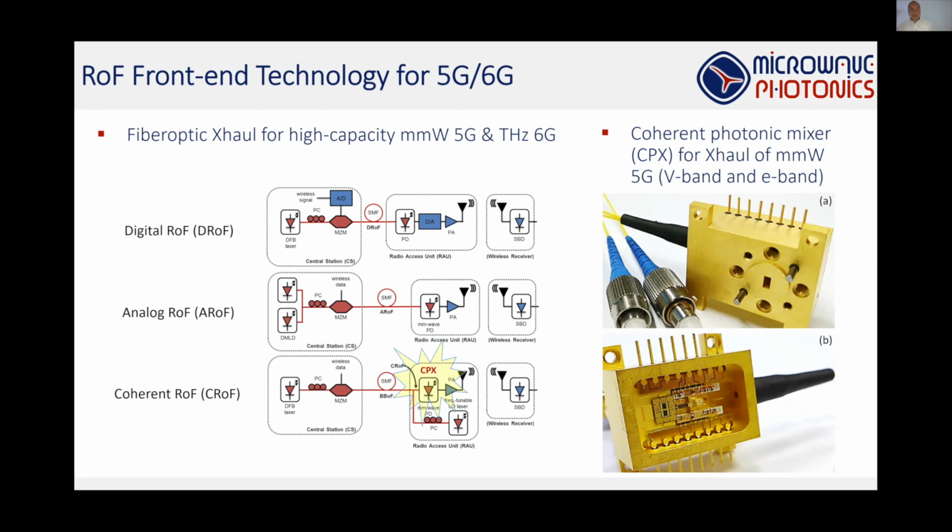Okay, so a balanced photodiode basically is two photodiodes in anti-parallel. And if you do your, let's say, mass calculation, what it is doing is you have two fiber inputs. One fiber is supporting the baseband optical data, and the second fiber puts an optical carrier. The frequency difference between the optical carrier and the baseband data is exactly the RF frequency.